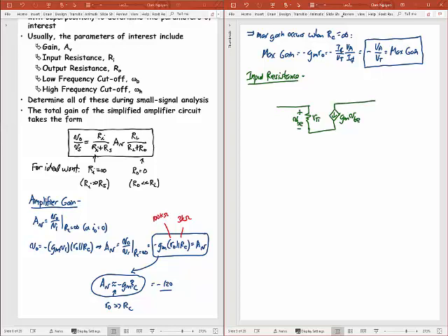Across this I'm going to have an output resistance R naught. And then around this whole thing, for biasing, I'm going to have my RC resistance. This is going to ground in the small signal circuit. At the input, I'm going to have a resistor here, R1, in parallel with R2, which is part of that bias string there. And so this is where I want that RI.